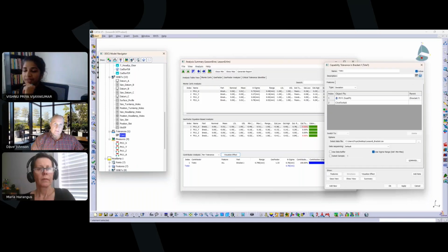Okay, that's a great question. Right now, the way it is set up, the preference is the place where you globally control the refinement. Users can manually do the refinement on their GD&T individually with no issues. But if they have to do it with the auto refinement setting, it has to be done globally. So the preference is the place where you set the refinement value, and that would be applied for all the GD&T that's getting created. I got you. So if they want to do it individually, just create an orientation and form callout in the GD&T. Okay.